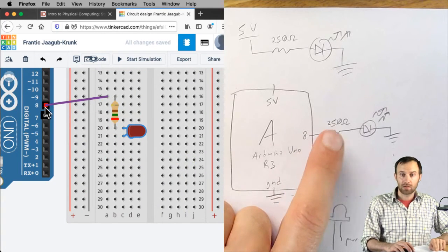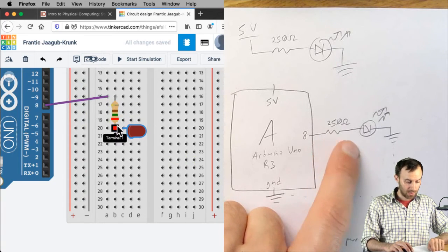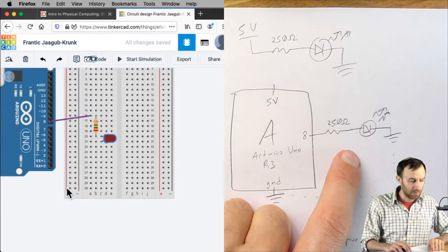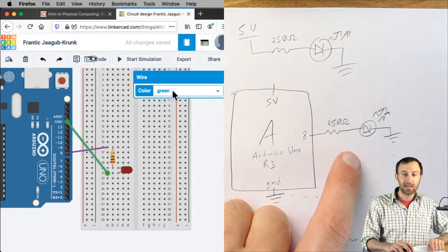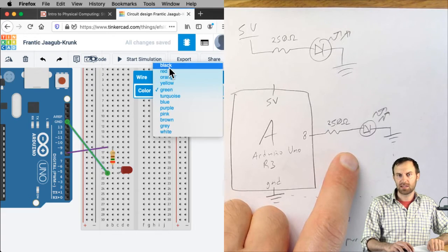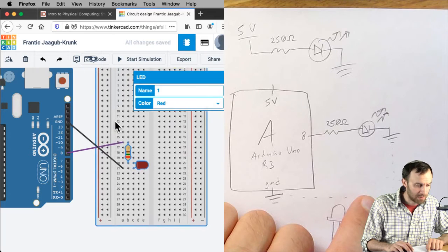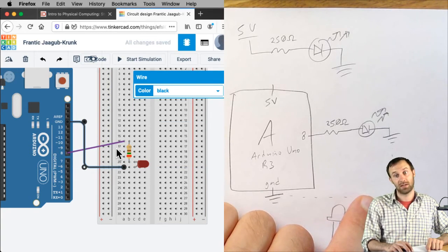So it's comparing, so we got the purple wire going here through the resistor, through the LED, and then the last thing it has to do is go to ground. Well, I'll just take a connection from here, click once, to ground, click once, and I'm going to change the color to black because that's the conventional color for ground wires. The last thing I could do, I'm going to move the board a little bit, is just double click these, and I can make nice straight little paths. That just pretties things up, and it makes it clearer how wires are connected to things.